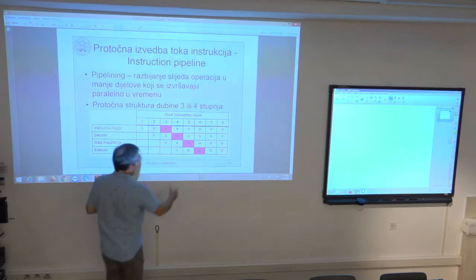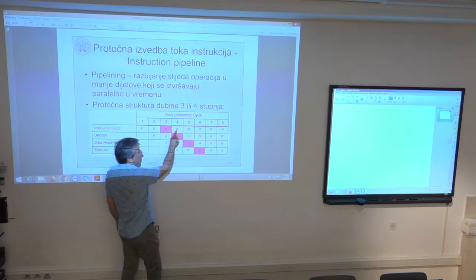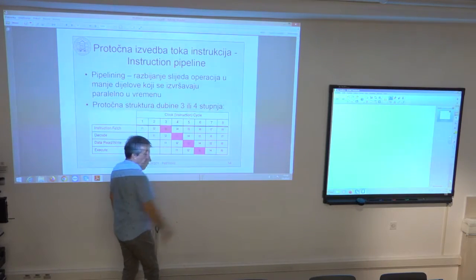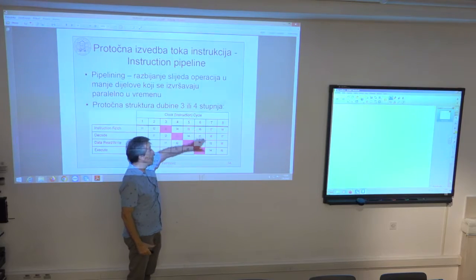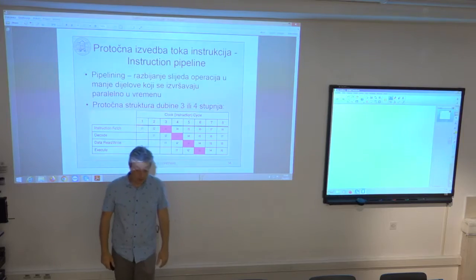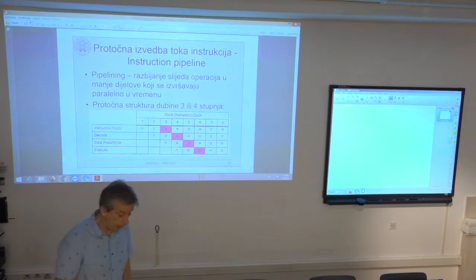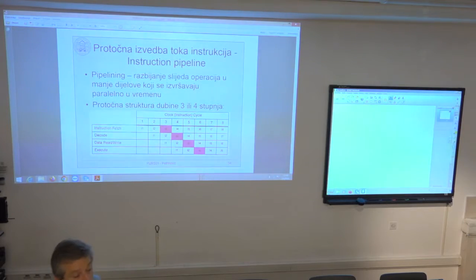But if the next instruction is a conditional jump, it already had to fetch the next address here. And the actual condition is set here. So I actually have to wait 3 states until the condition is set, and only then I can fetch the address either from the top of the loop or as the next address. So you would have 3 cycles of stalling the pipeline. But if you have this hardware-implemented do loop, it knows automatically in advance where it has to branch. What will be the next fetch address?